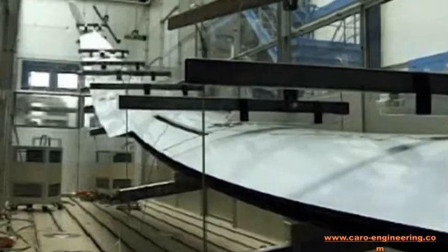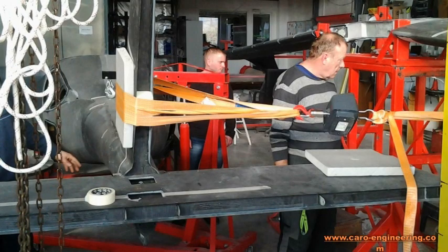The alternative is to use a whiffle tree with an actuator to apply the bending, shear, and torsion as in this picture. It is not necessary to test both wings together if they are joined in the center. A substitute structure can be used to keep the other side shorter. The fuselage is tested by applying forces to the engine mount and tail structure while it is supported at the wing attach points. For a prototype, it may be acceptable to load the structure to limit load only in order to prevent potential damage at ultimate load. Otherwise, a dedicated structural test article is used to test to ultimate load or failure.